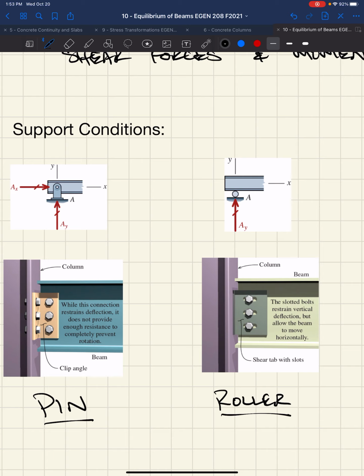So we preemptively compress it so that it stays in compression all the time. That minimizes cracks and increases capacity. Where you had walls 16 inches wide, you can get down to 4 or 5 inches thick. It's super thin, and actually really scary. Okay, diverged for quite a while there.